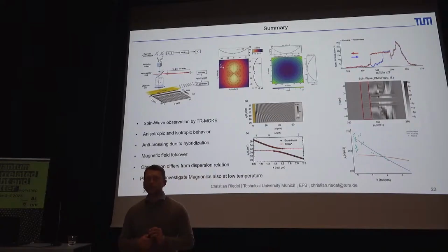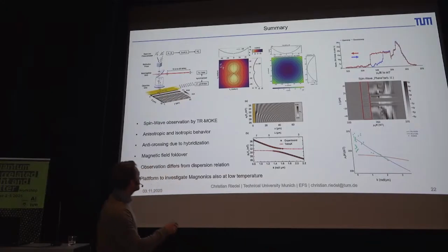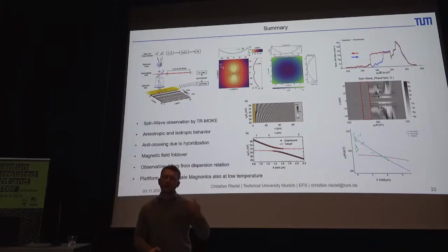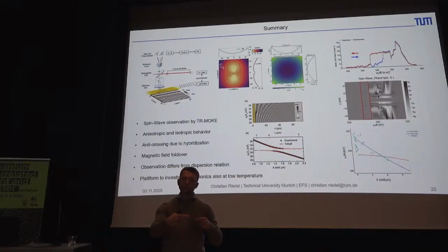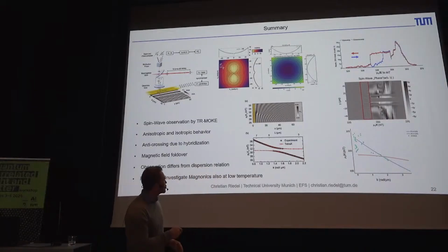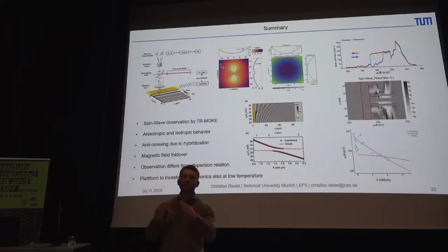For example, what we have shown is we have used this area here to make a hard stop for our propagating spin waves at a certain position. Because if you use an in-plane magnetic field and you have a wedge, as you just suggested, then at the border of the edge you have a reduced magnetic field because of surface charges, and that can allow you to shift the dispersion in this area just by the shape anisotropy. This we already showed, and there you get your abrupt stop.